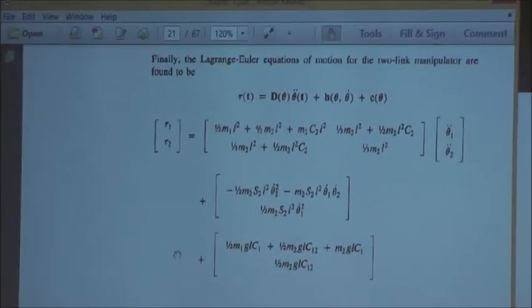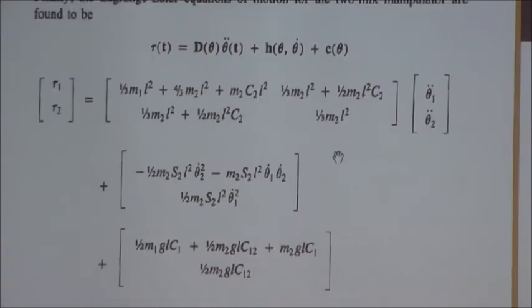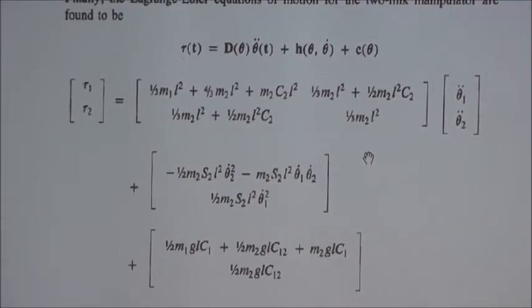Of course, in your experiment number 1, you will repeat homework number 1 in the lab. And you will do one link and 2 link inverted pendulum. So this is essentially the dynamic model of your 2 link inverted pendulum type. It's not exactly this because this is hanging down, the inverted pendulum going up. But nevertheless, you're supposed to do a linearization around that point, 180 degrees up, and then solve your control problem. We'll see you next time.